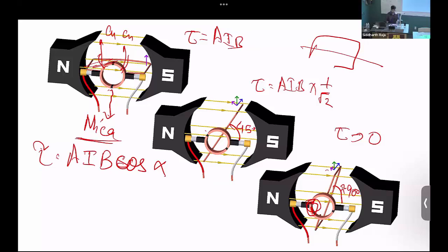You're breaking the current that's flowing through the winding of the rotor, which would then cause a huge arcing, which would then burn away the brush or create some arcing or burn away the winding. All right, so the first one is a problem we can fix. If you short two copper rings, we just need to make sure the voltage in that loop during that time is 0, which we can work out. But breaking the current in a conductor, that is not a solvable problem, right? And again, you can't put a diode or a rectifier, none of those things here.